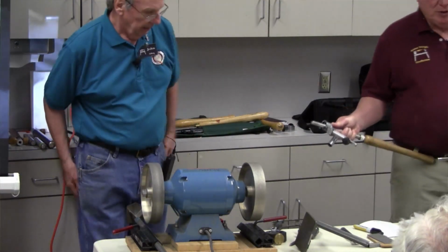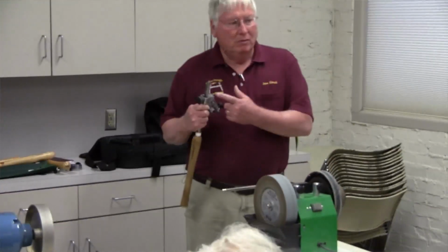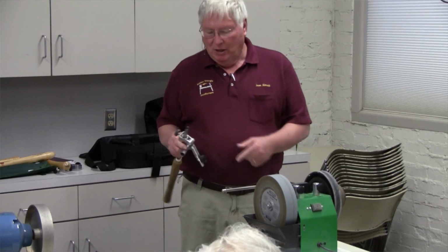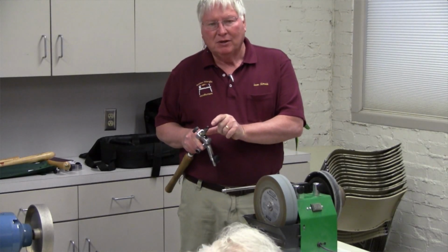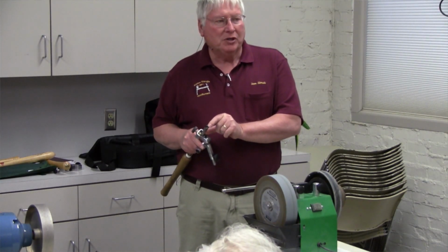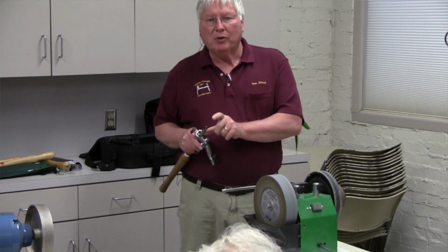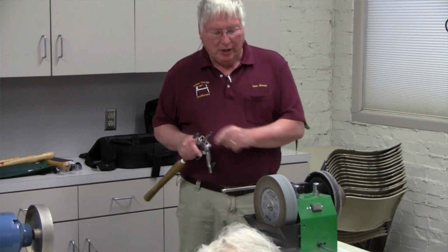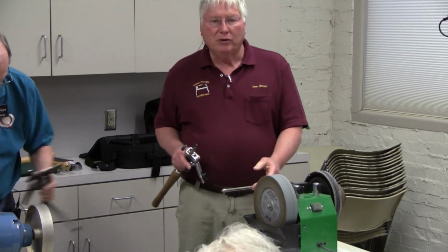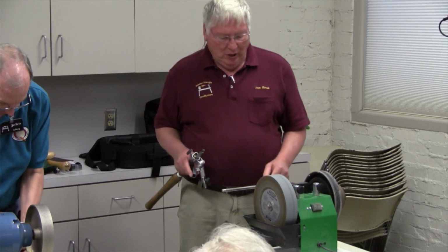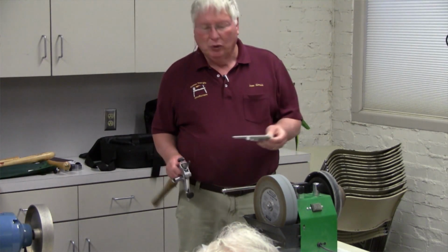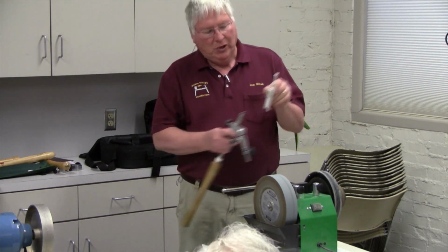So much like with the Wolverine system, again, you can monitor the angle, set the angle depending upon how far back you want it to sweep. You can set the distance that the tool extends from, or the gouge extends from the tool, which will help you in determining what profile you're going to end up with. And then again, the distance from the control bar here to the edge of the wheel. The nice thing is that there's a handy dandy little tool that allows you to very quickly set the depth.